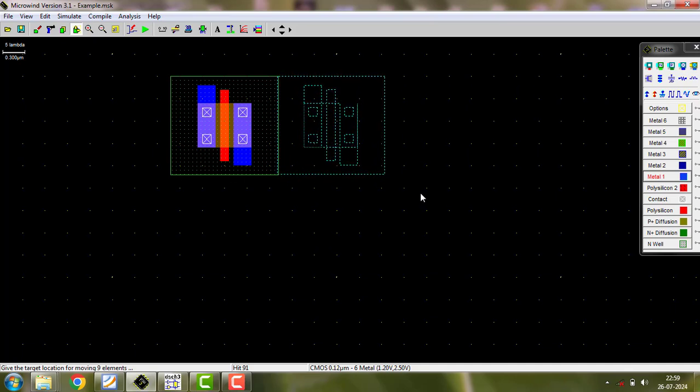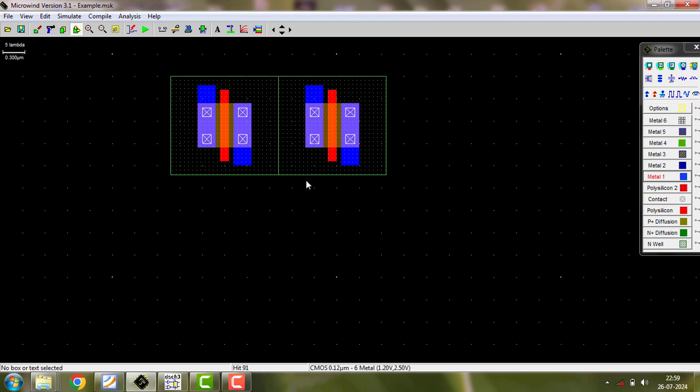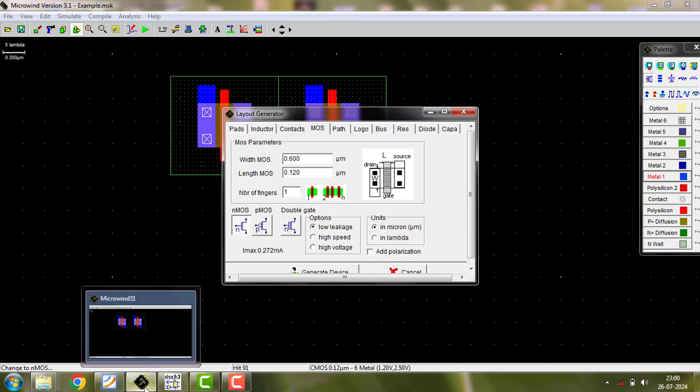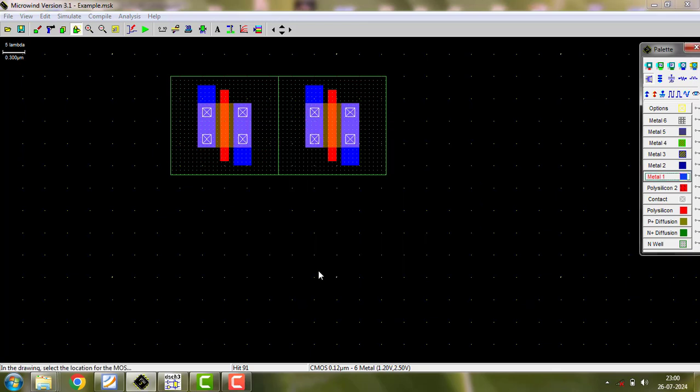I am not connecting. Okay. So this also works. Nothing wrong in it. Similar to that, I have to take NMOS. I have already decided this must be twice the size of the minimum. Okay, I have to move it such that I can connect it easily with the gates, and the gates I would like to short.